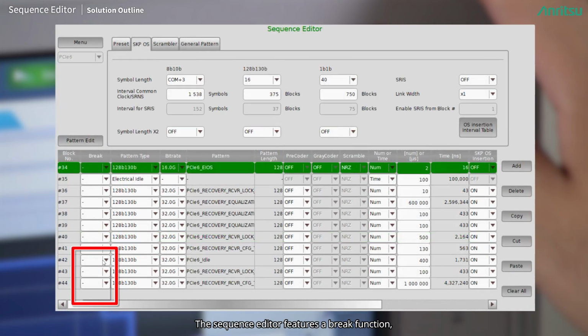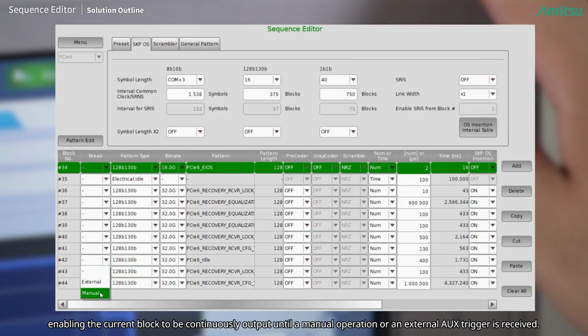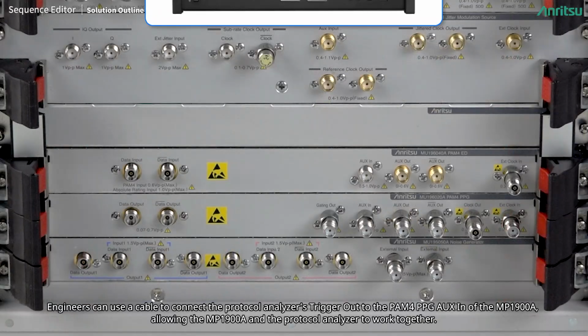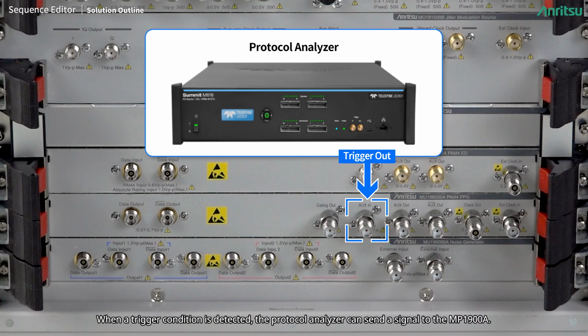The sequence editor features a break function, enabling the current block to be continuously output until a manual operation or an external AUX trigger is received. Engineers can use a cable to connect the protocol analyzer's trigger out to the PAM4 PPG AUX of the MP1900A, allowing the MP1900A and the protocol analyzer to work together. When a trigger condition is detected, the protocol analyzer can send a signal to the MP1900A.